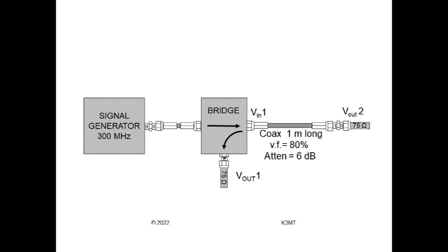Driven by V equals 2 plus j0 volts, its output is 0 minus j1 volts. And, as it drives a resistive load, the input and output current are in the same ratio with the 90 degrees phase shift. By turning the coax around, we get the same measurements, so S11 equals S22, and S12 equals S21. This two-port network has 2 squared, or 4, S parameters.